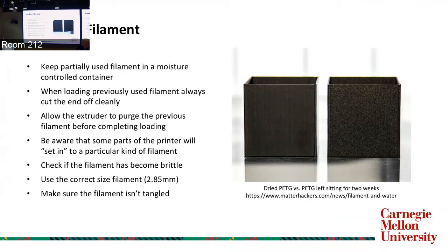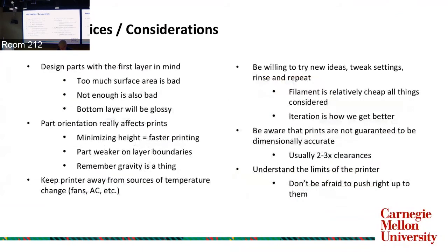You can see good filament versus bad, and we'll talk with Brad and see if we can get some procedures on that. And then finally, sort of my tips slide. I have a couple other of these that are on the longer slide deck, but do really pay attention to the first layer.